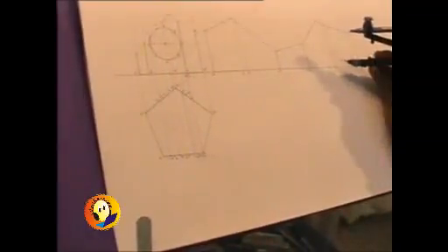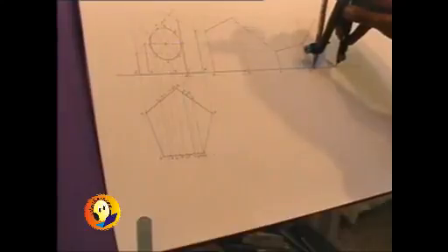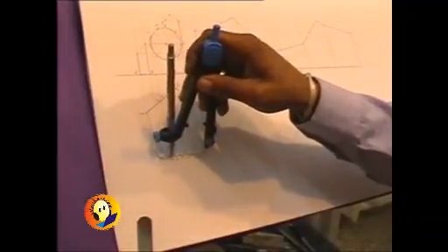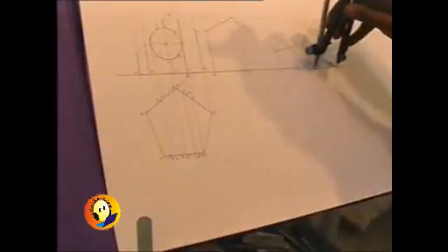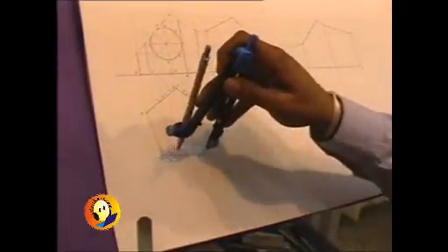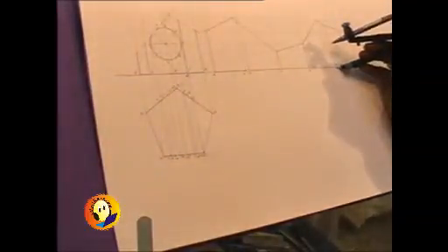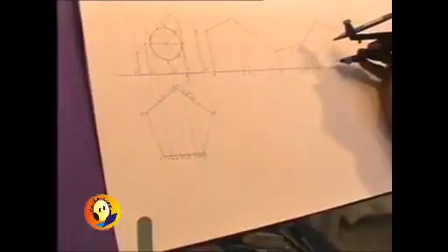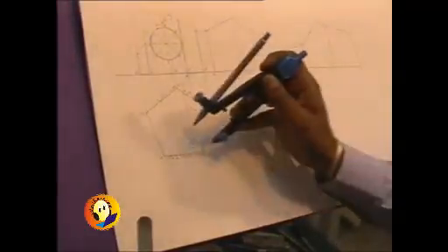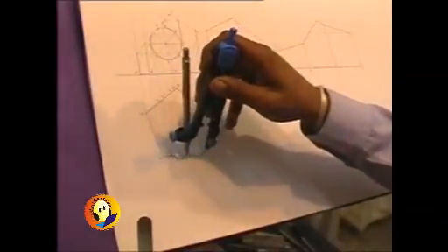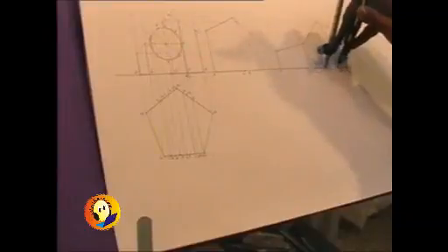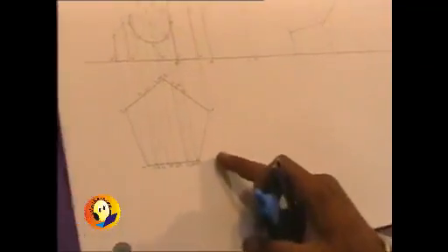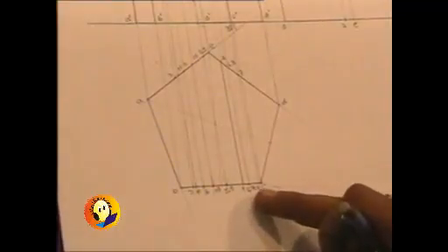So on the development it will be from C towards B, generator 3. Then we have point 11. From C towards B, mark that 11 distance. Then take distance C4 and mark it from C towards B. Then C10, mark it. Then we have C5, this is 5 as well as 9. And to mark C6 and C7, the distances which are pretty small over here,